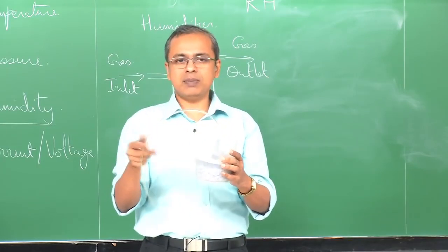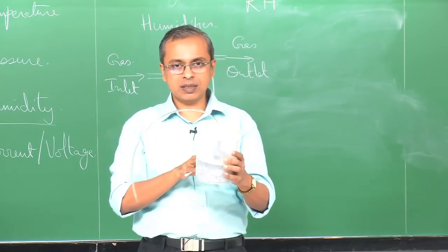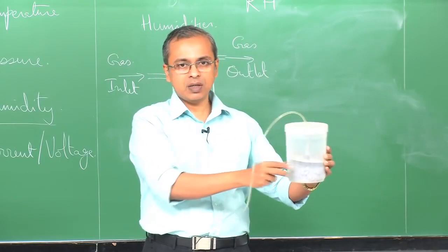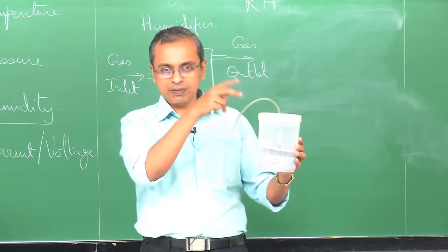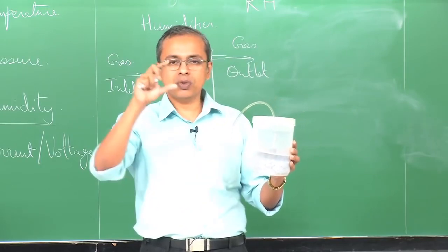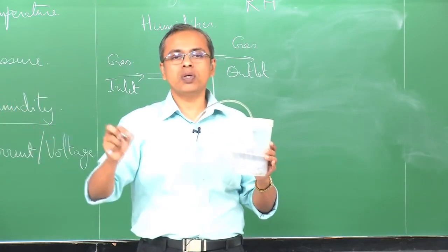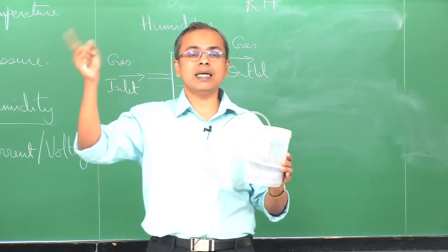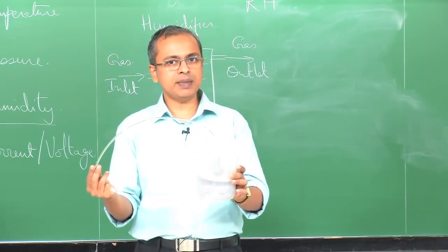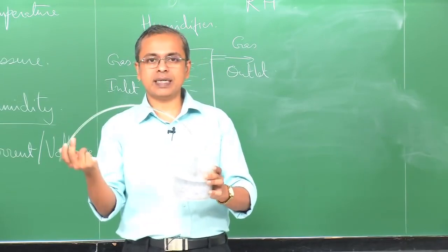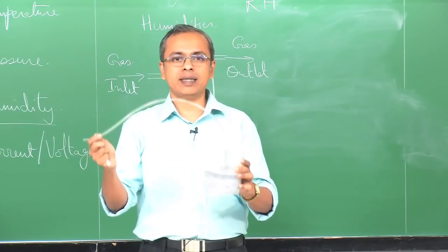And then when you continue this experiment for some time at some fixed flow rate, you can know how much volume of gas went through this, and then you take this bottle and weigh it. You know what is the gain in weight. That gain in weight is all the extra water that got collected in this box, which was captured by the desiccant. And so, you know that many grams of water was carried by that much volume of gas, and therefore, you know the humidity of that gas, because you know theoretically that same volume should have had how many grams of water. So, this is a simple experimental setup, but it is a very good setup because it helps you analyze and get a good idea of what is the actual humidity that is there in the gas that you are using, right.